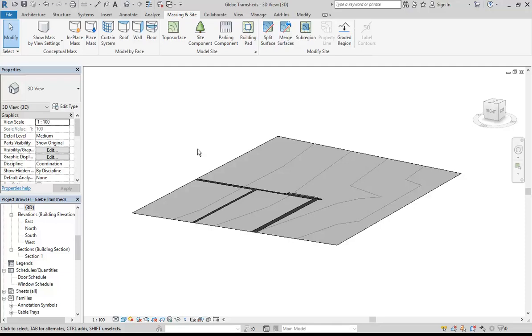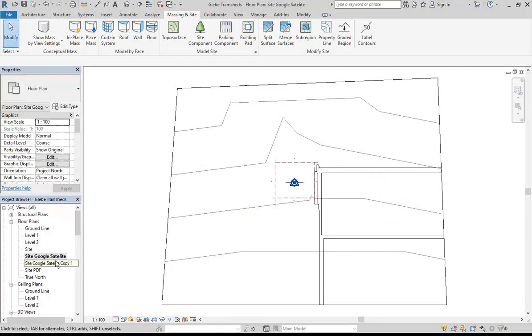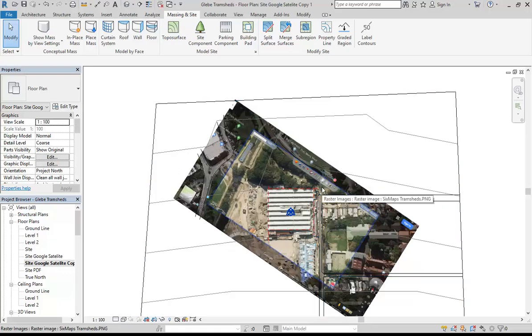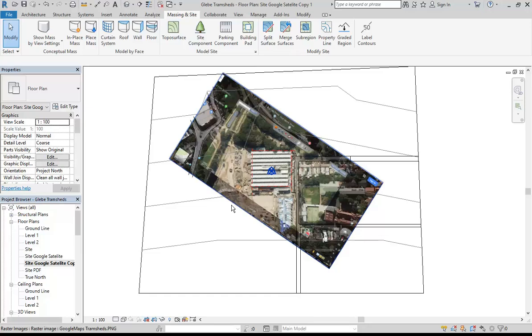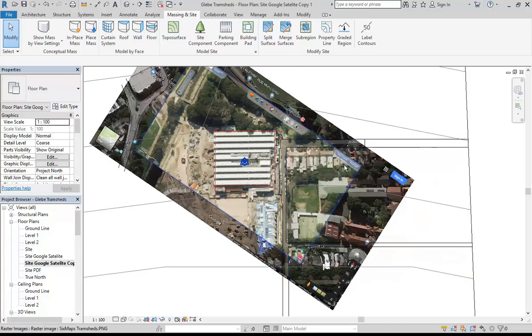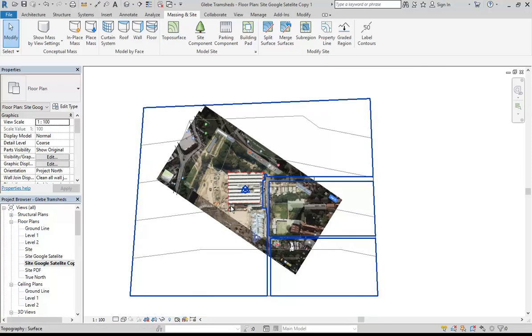But I would recommend, because it seems like quite a few of your projects are pretty close to the water, that's the only time I use split surface. So when you've got water, which I didn't pick up here, but the water's up there, you can do split surface and then just flatten out all of the water, because obviously the water is flat. But we'll maybe look at that later. So for now, I'd recommend just keep the whole surface as one topo surface. Try to get some heights if you can, but if you can't, just keep it fairly flat. And there's nothing to stop you drawing in the detail for your roads and other pathways and things going around your site. And then as you get your heights, you can come back and add those in.